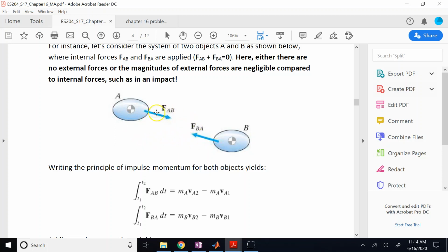Now, during that impact period, is there no other external force? Well, typically, yes, there is. At least we can see the gravity is always there regardless. So can we neglect it and then say that because there is no external force on this system of particles, the total momentum of the system is conserved? Can I say that? Because that's exactly what we do when we solve impact problems. So we neglect the gravity.